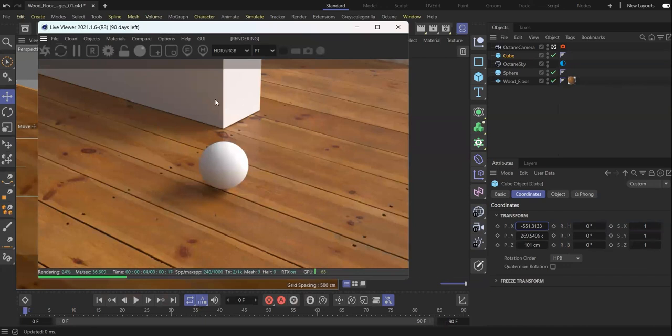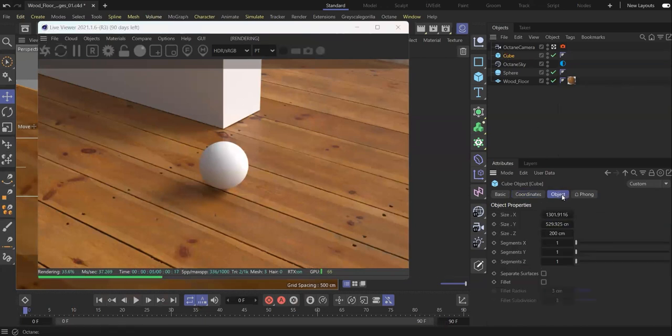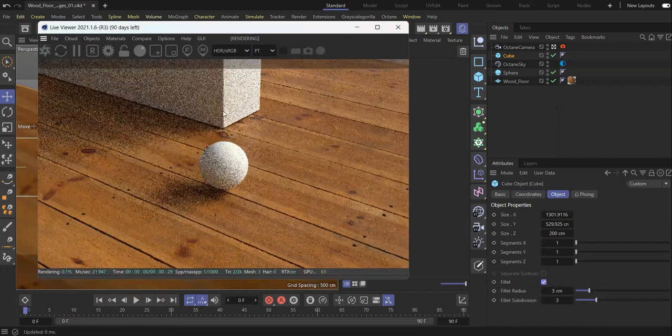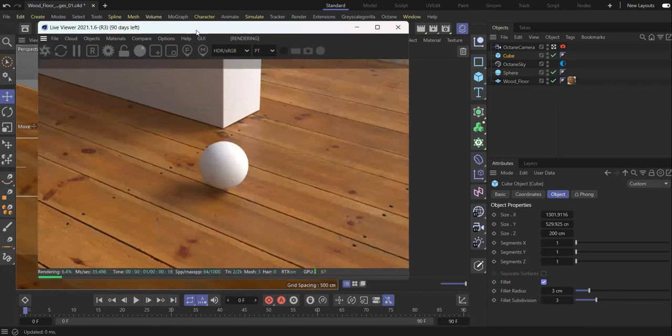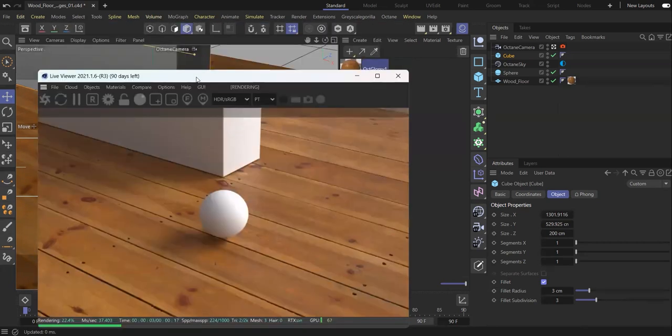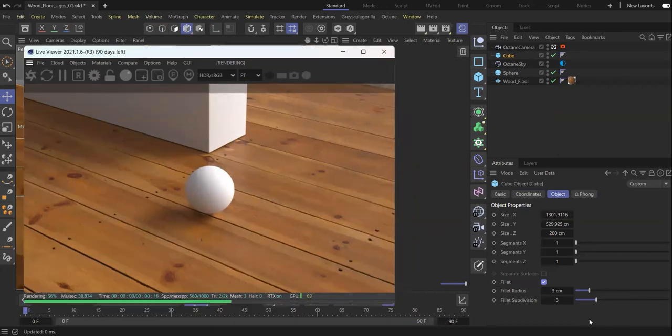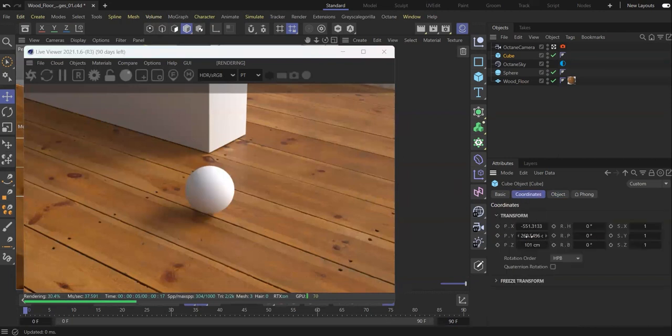Now, I'm not going to focus too much on the wall here. I will add a little bit of a fillet. You never want to have no rounding on a corner. That doesn't mean everything needs to be very bubbly and soft and rounded, but you don't want that one pixel CG edge on anything, whether it's stylized or photorealistic. So I might even change this radius and make it a little bit smaller to have a sharper corner, but having those corners is very, very important to what we're making.